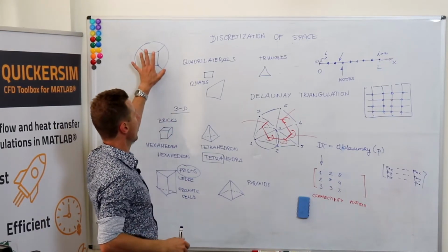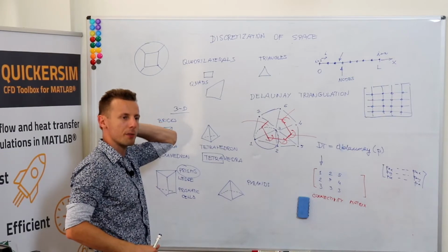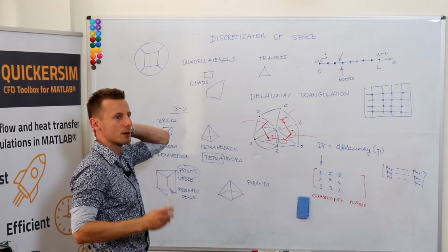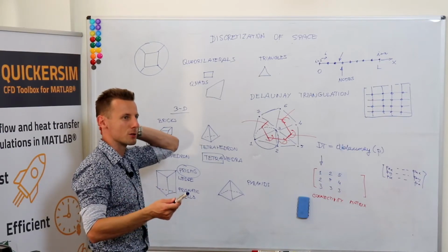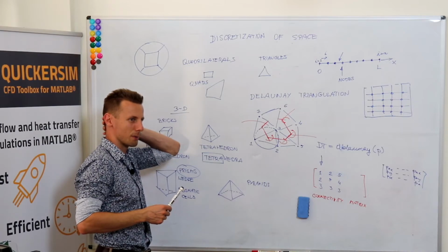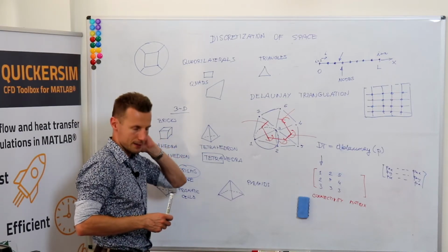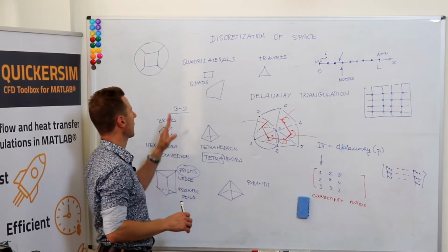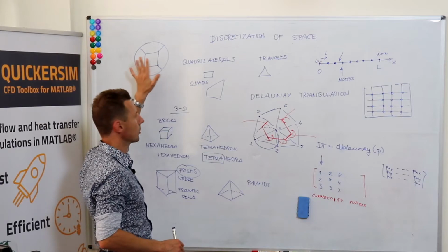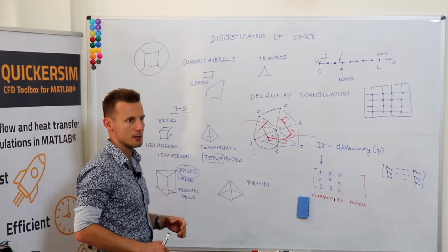So you can probably always subdivide into quadrilaterals, but certainly there exists no automatic way of generating structured meshes, because quad meshes you can probably also still generate automatically, but they will not be nice. Exactly. So without going into theory, for practical applications, you will not find good ways of generating quad meshes automatically.